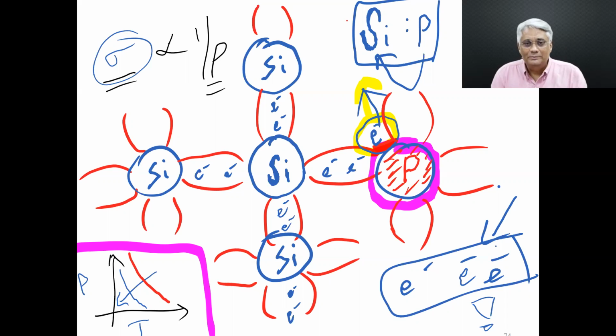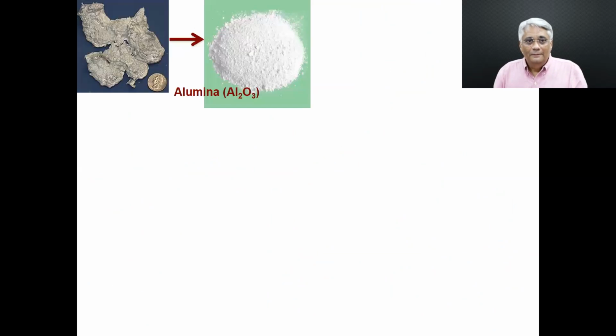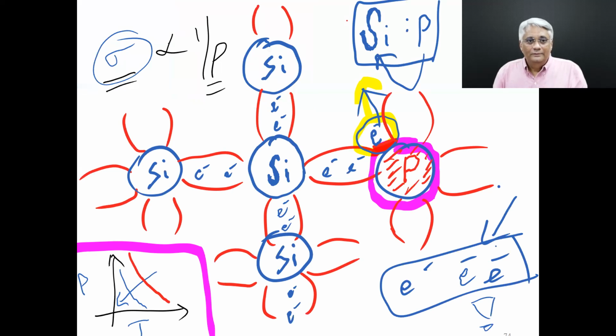Even if you're doing Hall measurements on a bulk sample, one would like to reduce the thickness of the bulk sample. So if you're doing the same measurement on a thin film sample, naturally the thickness will be very small. You're dealing with a few hundred nanometers of thickness of the sample for Hall measurements. That's why Hall measurements on thin films are always viable.